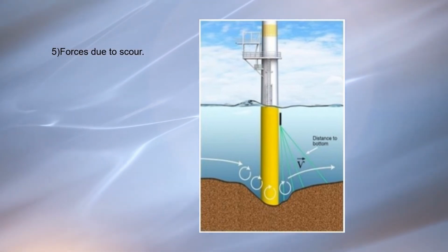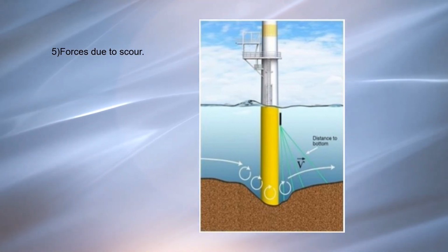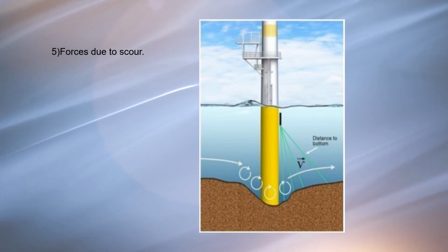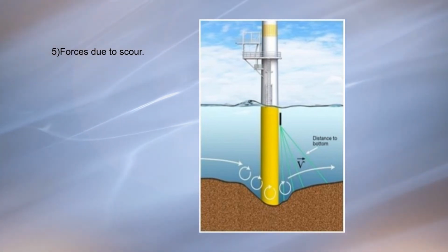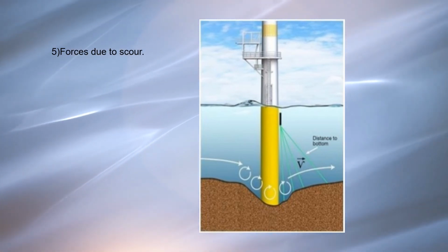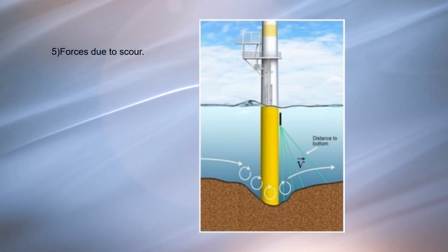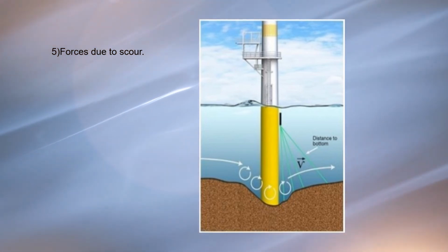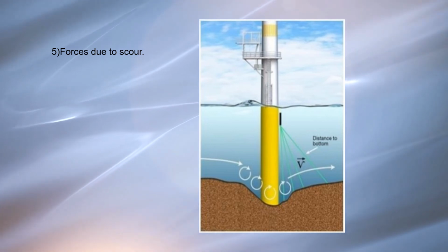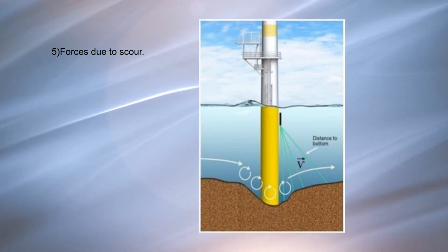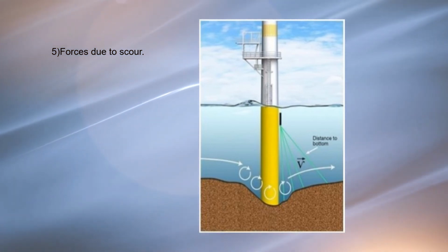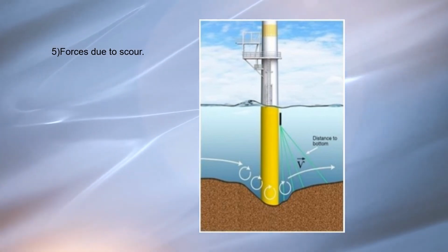A very practical method of preventing scour is to deposit a blanket of crushed rock or heavy gravel around the cofferdam, either before or immediately after the cofferdam sheet piles are set. A more sophisticated method is to lay a mattress of filter fabric, covering it with rock to hold it in place.